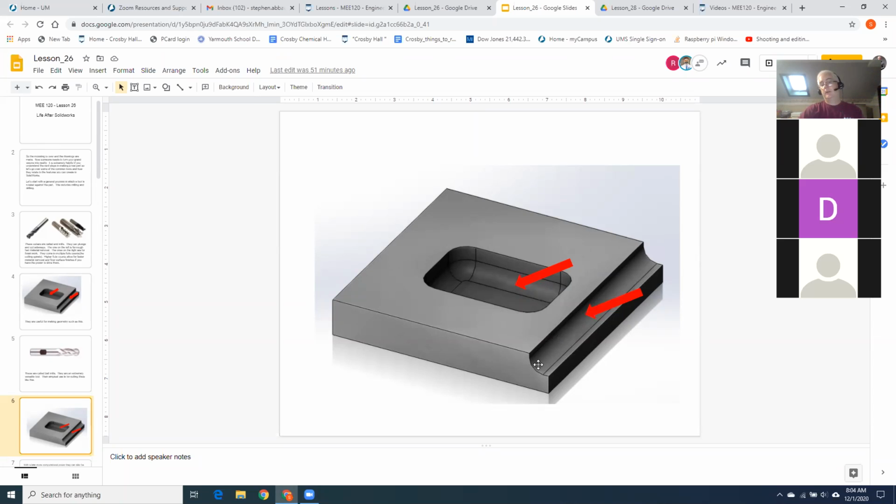Now, remember, for example, on this corner right here, I still have to have enough room for the rest of the ball mill right in here. So as you're sitting there dreaming up these amazing parts, I want you to think about that tool and think about, okay, do I have enough room to get it in there? You're probably not familiar with the heads, but start thinking about what is the tool that's going to make this. Can I fit it in? Stuff like that will go a long, long way toward helping you get through your first design reviews out in the real world.